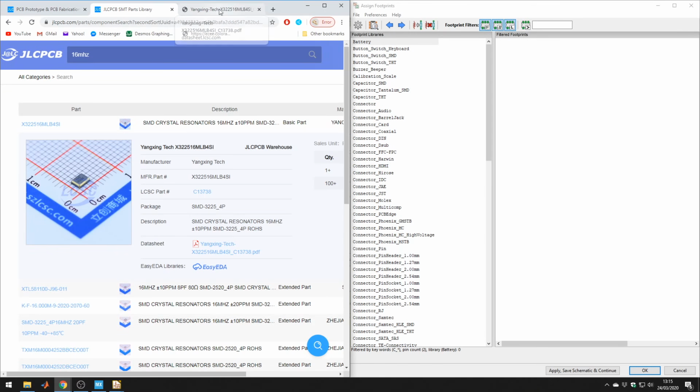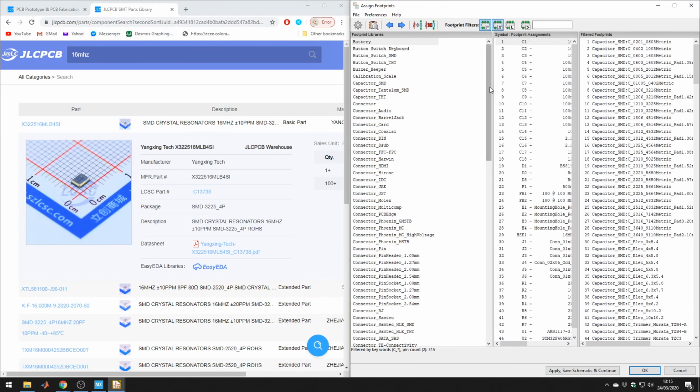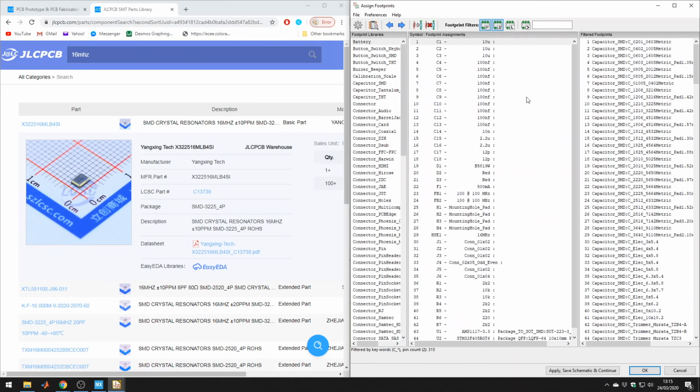So, I don't know, deselect that, stretch this out. Okay. My general rule of thumb is the larger the value of capacitance you want, the larger the footprint. This is because the voltage rating of the capacitor will also be higher, and generally you want to maximize the voltage rating of the capacitor. Even if you know there are only going to be 3 volts across the capacitor, choose the one with the highest voltage rating.